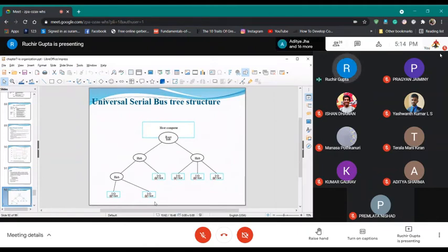What happens actually is that all of these, whether a hub or an IO device, are assigned an address of 7 bits. In a way, from the root hub, every hub or device behaves in the same way. Whatever comes from the root hub is transferred to all the hubs and all the devices. And it will be useful for someone; only that device will respond, no other is permitted to respond.